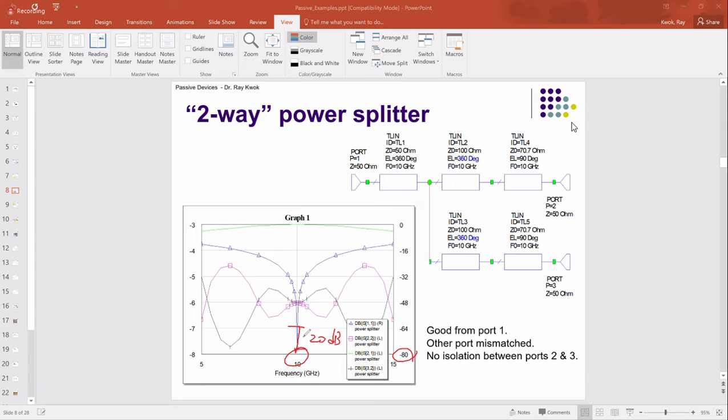Remember, the lower this is, the smaller the number. This is 10 to the minus 8. To go from 10 to the minus 8 to 10 to the minus 6 is not that big a deal. If you go 10 dB or 20 dB on top, that's a big deal. If you go from 1 to 0.01, that's a big deal, right? That's like a drop of 99%. But if you go from 10 to the minus 6 to 10 to the minus 8, your fluctuation is less than a microwatt, right? You would have to move a few watts to do that, so this can change easily. That's why these are noise, right? Typical return loss is minus 15 to minus 20, I would say.